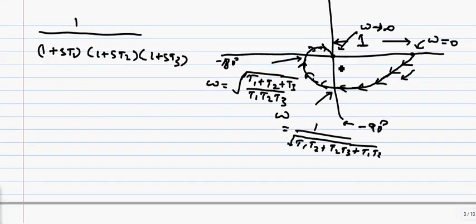And we are not concerned about the magnitudes here because the equations become really lengthy and it's not actually worth remembering them. Okay, we will see situations where, when we are looking for the stability of a system by using Nyquist stability criterion, we need to usually look for the magnitude when it is crossing the 180 degrees line, which is the negative real axis.